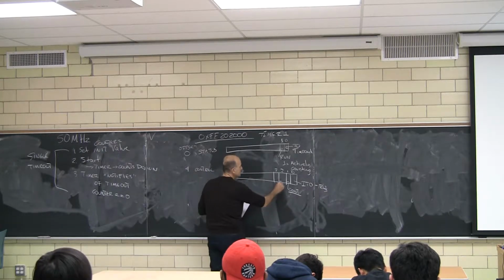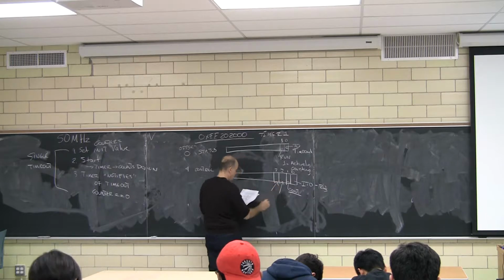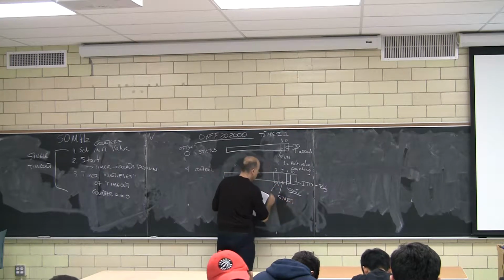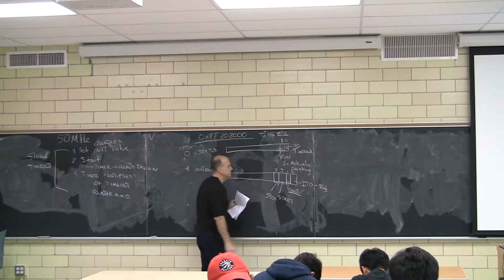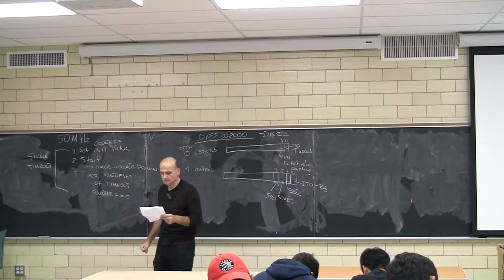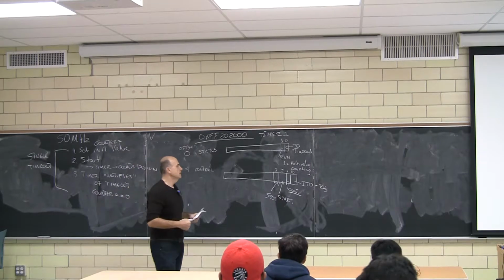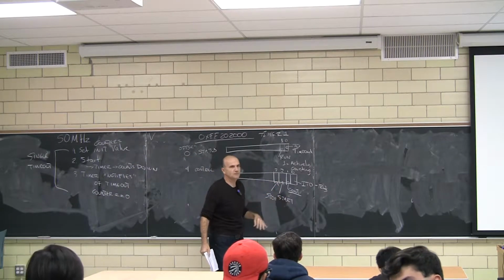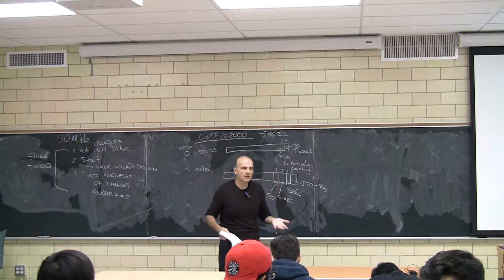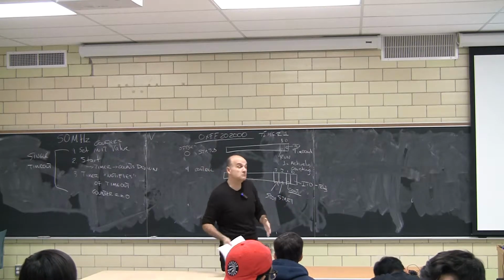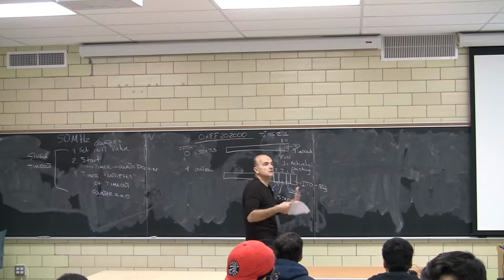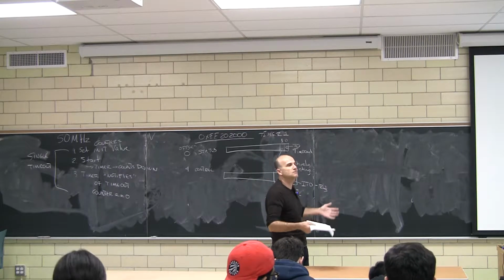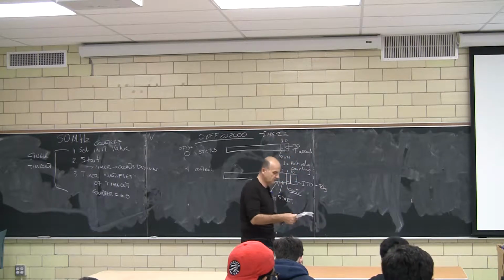Now, and these are really commands now. There is the start, and there is the stop. Fair enough? And you're not supposed to write 1 to both of them. You're supposed to say one of the two. If you say both of them, something will happen. Again, it's undefined behavior. Who knows what? Don't assume that it will always be the same. Don't assume that in a future version of this hardware, it's going to be the same as it is right now. That's what it means, undefined behavior.